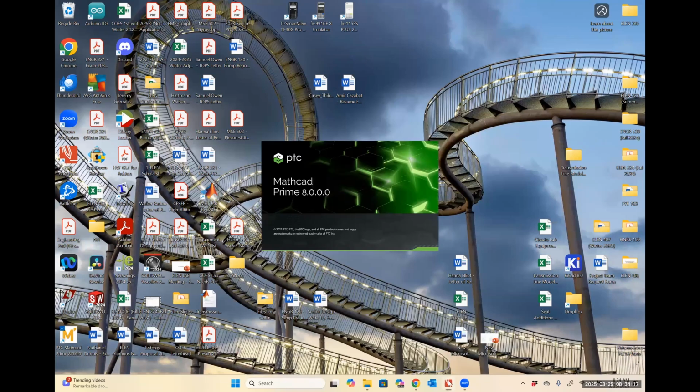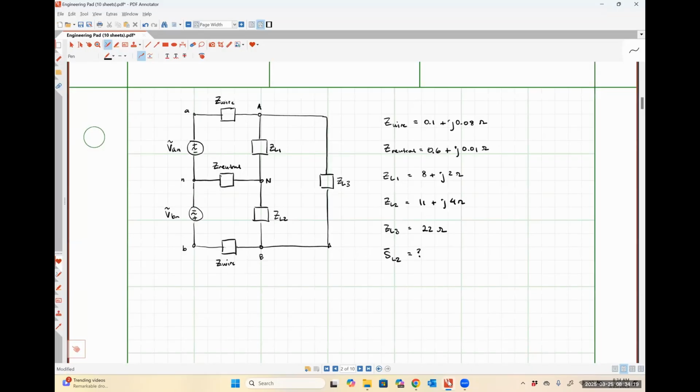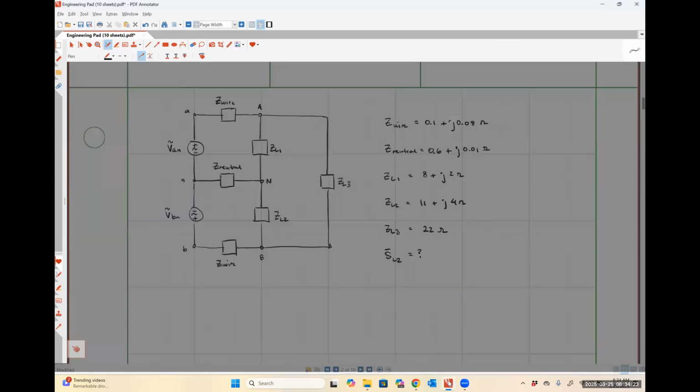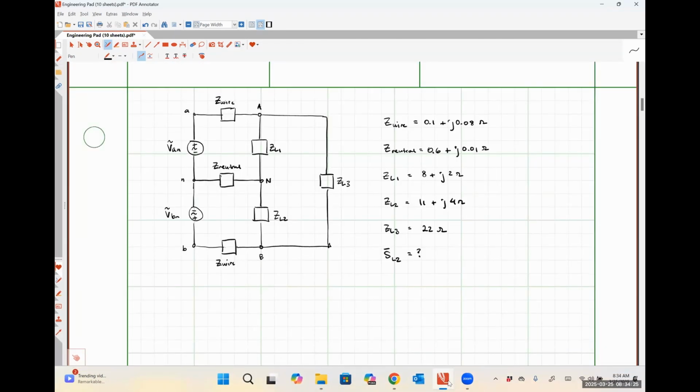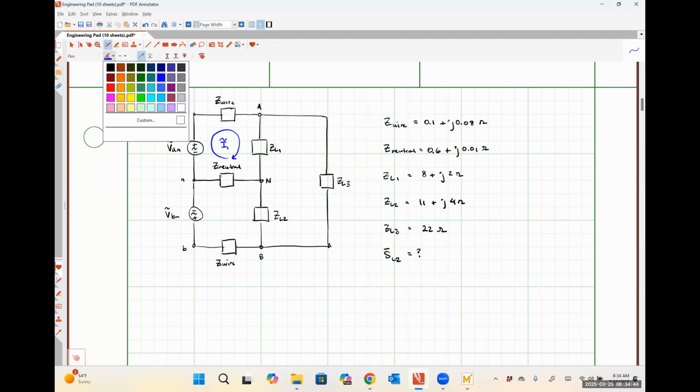We are going to perform our circuit analysis here, okay? So I'm choosing to use mesh analysis in this particular case just because this system only has 3 meshes, and it has a whole bunch of nodes. So the mesh circuit analysis is going to be an easier system to set up. I'm going to define my mesh currents. So here is going to be my mesh current I1.